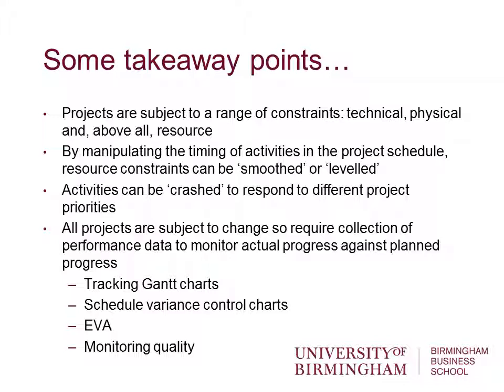So, manipulating the timing of activities in the project schedule can help to smooth or level resources which are going to be used throughout the project, so we can optimize it in that way. And activities can be crashed to respond to different project priorities and optimize the project in that way as well, by removing float, but then the cost of that is to introduce risk.